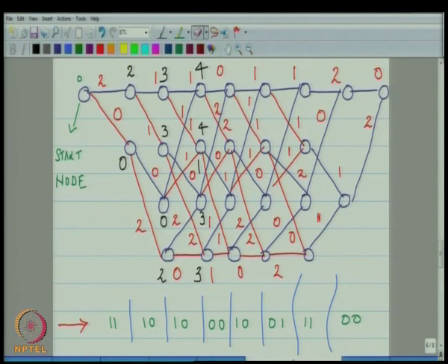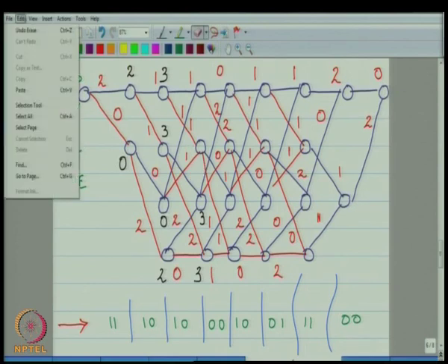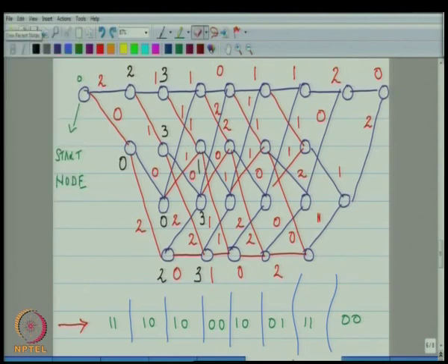You say, wait a minute, I can't quite do that, because in reality to each node now I have 2 incoming paths. So which do I choose? So I have to make a choice. So the answer is, as you might expect, you choose the more likely path. And this is where the rejection that I was telling you about comes into play.